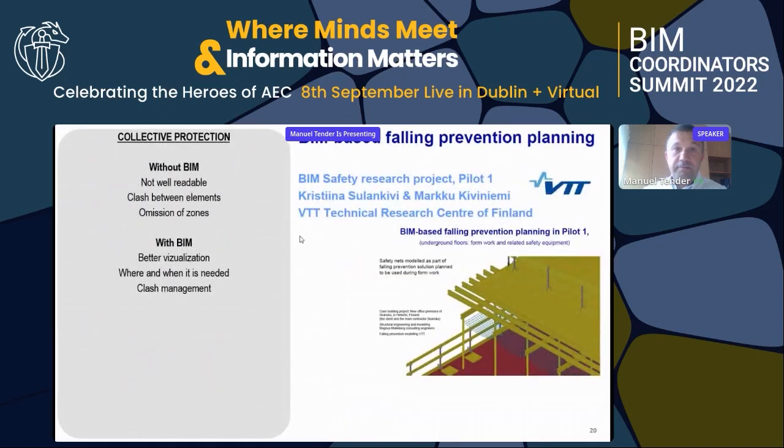In terms of collective protection, like guardrails, I also put here the example of VTT, which has been doing the modeling of guardrails for many years. Guardrails are usually not well understood in the 2D drawing, and sometimes there's omission of some elements. If I use BIM, it's easier to visualize what guardrails or safety nets I'm going to use, where and when they're needed, and if there's any clash management.